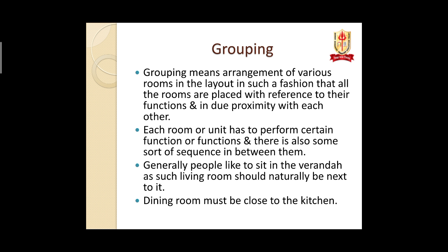Now we will come to grouping. Grouping means the arrangement of various rooms in the layout in such a fashion that all the rooms are placed with reference to their function and in due proportion with each other. Each room or unit has to perform a certain function, and there is also some sort of sequence between them. Generally, people like to sit in the veranda, so a living room should naturally be next to it. Dining room should be close to the kitchen.